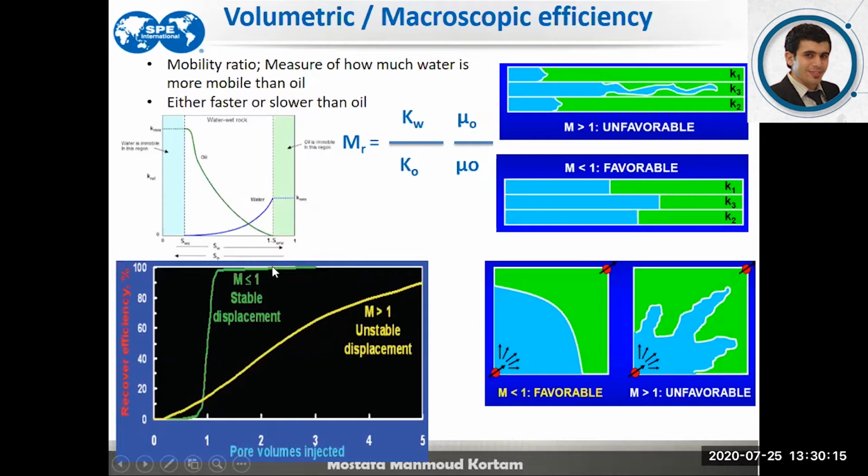which is still very far beyond the effective mobility ratio, which would result from reservoirs that have a lower oil viscosity and a greater oil permeability with respect to the water. So in the condition where we have a good mobility, and the mobility of water is closer to the mobility of oil or maybe less, we would achieve a good result by just displacing our reservoir with 1 pore volume. We would obtain a greater recovery over the one suffering from a poor mobility ratio.